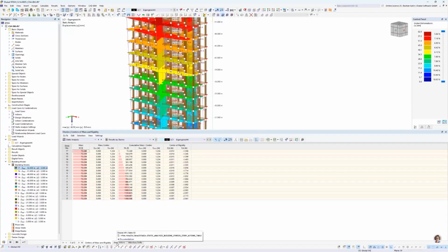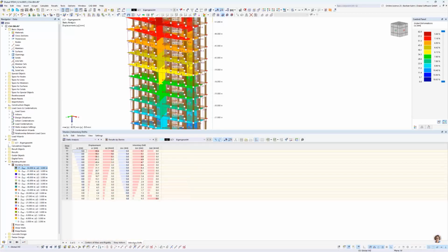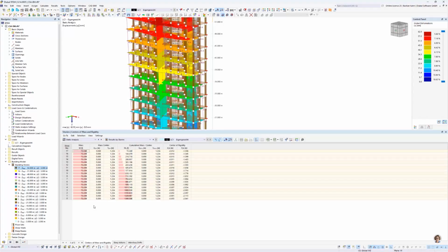For the load case that we have calculated, we have the story action, so we can see what force is applying in horizontal direction. So all the stiffening elements, okay, we do not have wind load or earthquake load in here, but imagine we have defined it. It would give us the information, this horizontal force is transported in X direction. How much mass do I have to activate in here? And we have the deformation of each story.